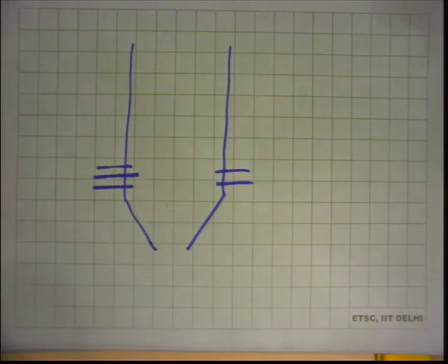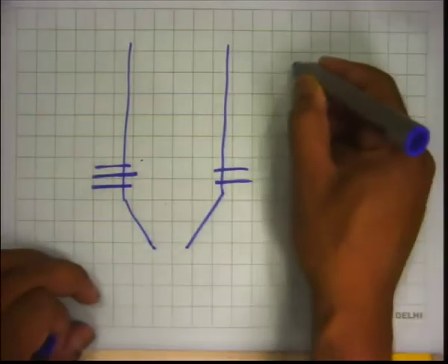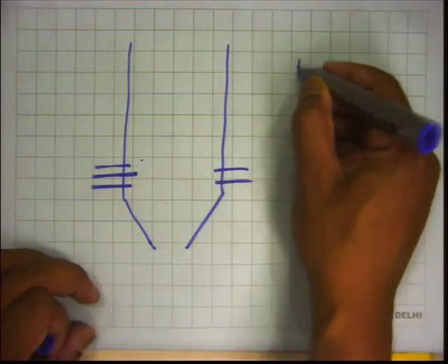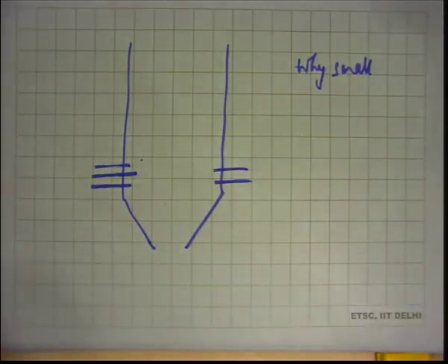Whichever kind of firing, it may be just opposed firing, or corner fired, or tangential firing, whatever. But you are sending these particles. So what are the questions? Why small particles? We know that these are small particles because we want to reduce the time that is required for combustion. Correct? That's obvious.